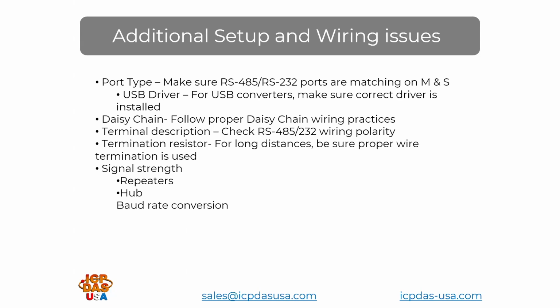Termination resistors are suggested for long distance wiring. For short runs, we usually don't use them, but in some instances, it may improve communication. So, please follow proper RS-485 wiring techniques. And with your electrician, by debugging, we can determine if they are truly required in your application.